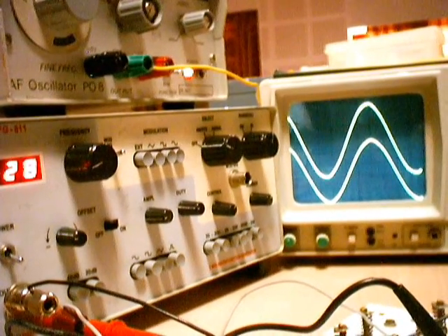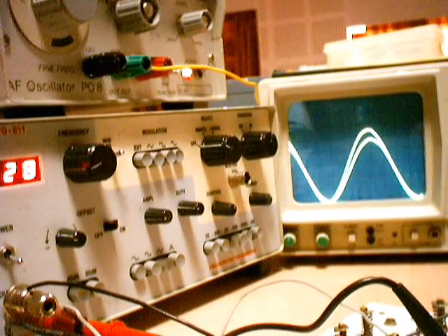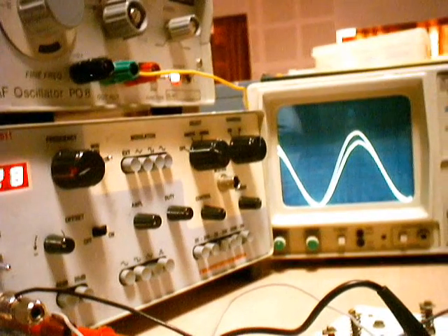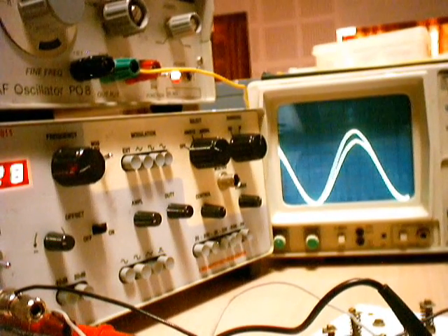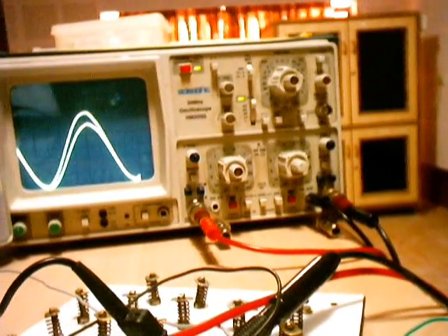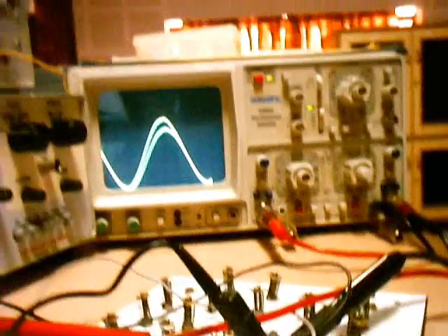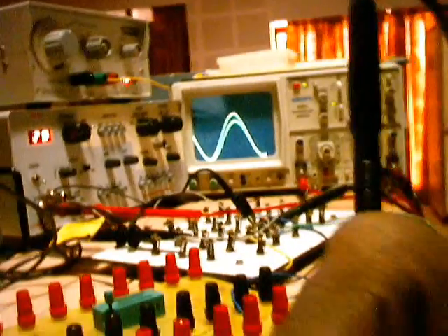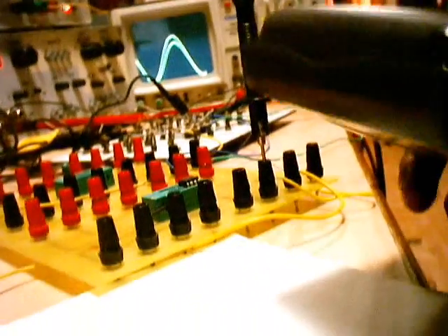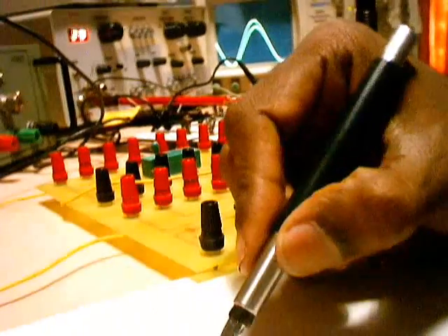So let us now measure the passband gain. The output voltage happens to be around 6.7 volts, and the input is 5 volts. We can find the gain in the passband. This V0 is now 6.8. The gain is 6.8 divided by 5, which is 1.36. We designed for 1.586, and we are having a gain of 1.36, so okay, it's fairly good.